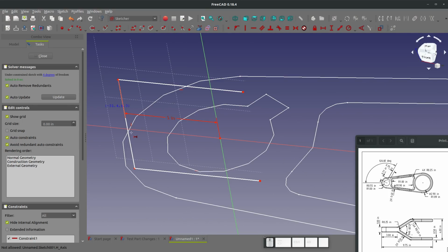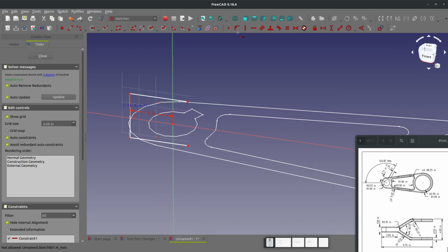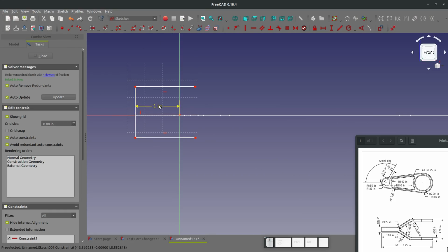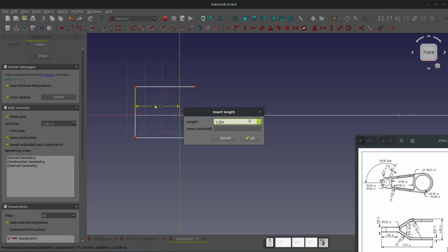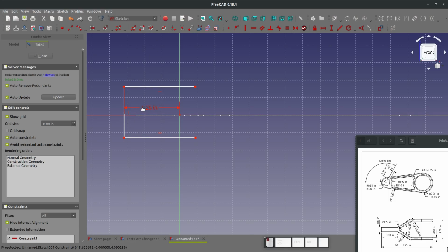Now you'll see that we're going to be doing a boolean operation, and there's a point at which these collide. That gives the potential of 0 thickness. The boolean will work, right? FreeCAD will let the boolean work, but it is better practice to go a little bit further out. And we can with our boolean because this edge will now determine where the part ends.